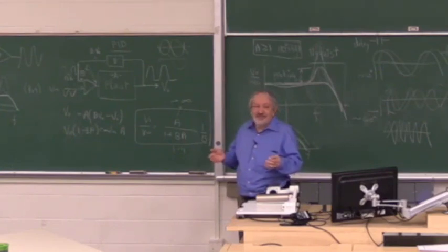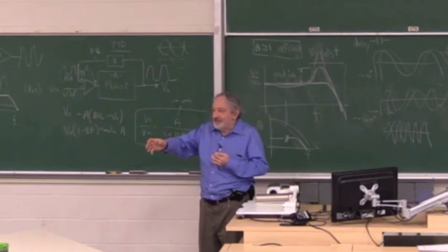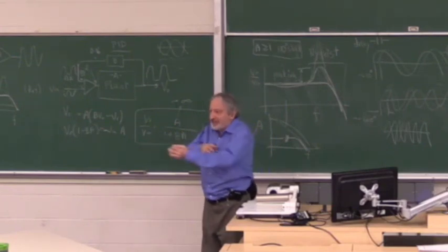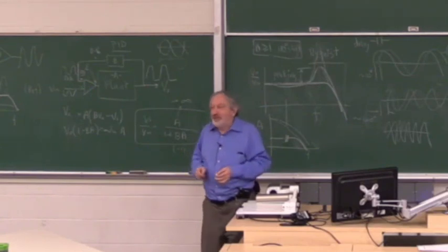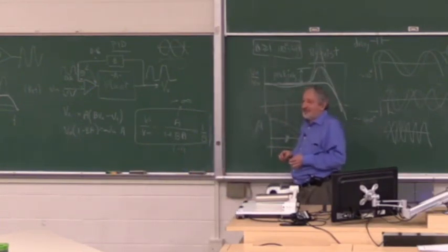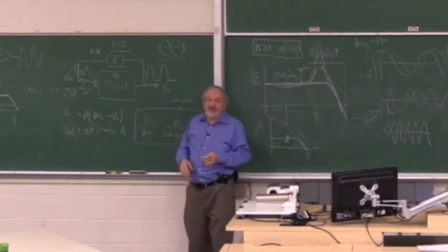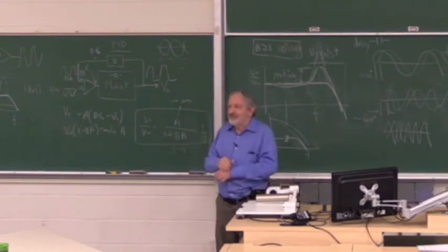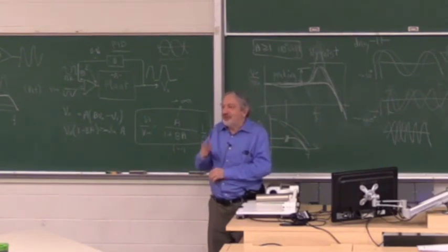Because at resonance, the driving force and the position are out of phase, and they wildly reverse phase. Just look at the graphs of a second order system. So any resonance implies wild phase shifts. And the wild phase shifts will reverse the feedback polarity, and instead of negative it becomes positive. And that's a big problem in servo systems. And if the resonance is very steep, the phase shift can be huge, much more than 180 degrees.